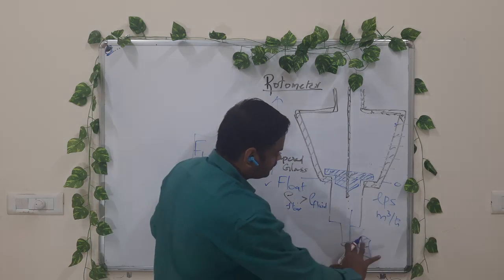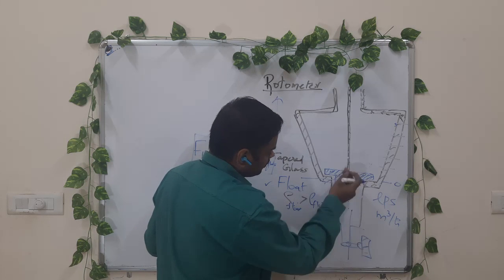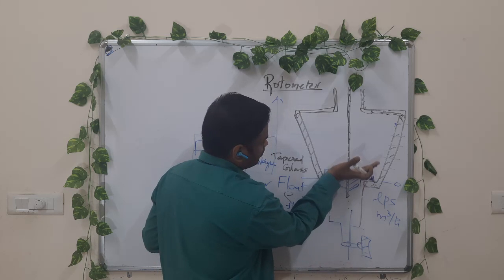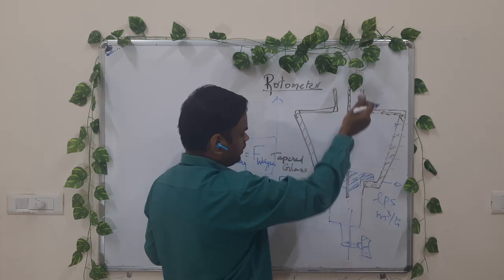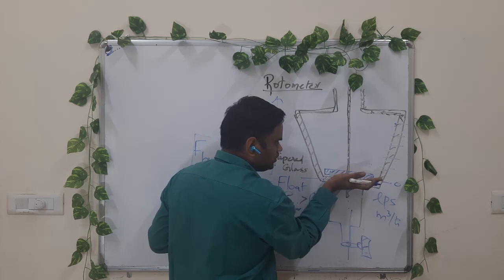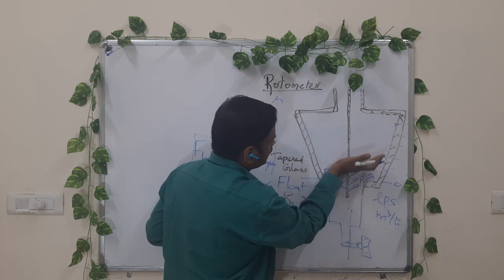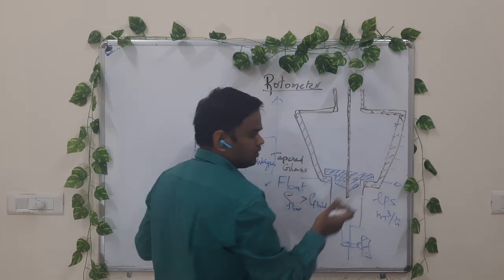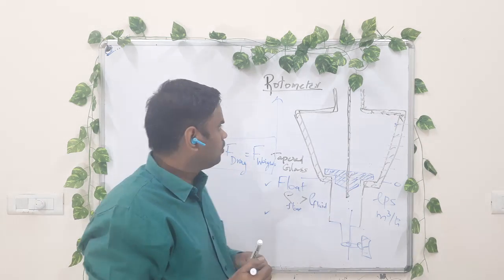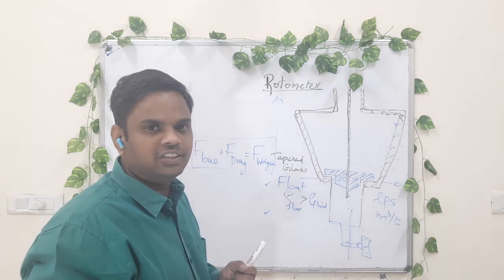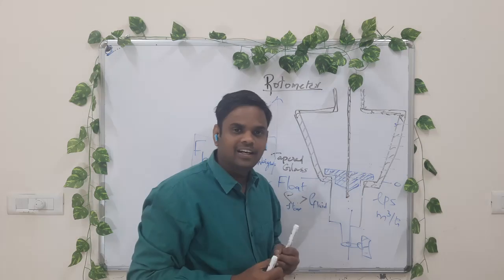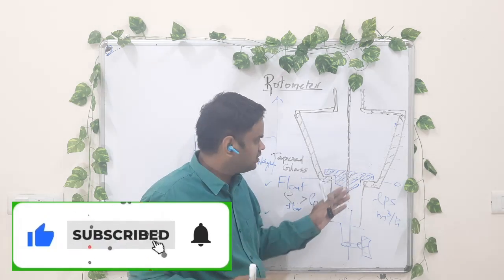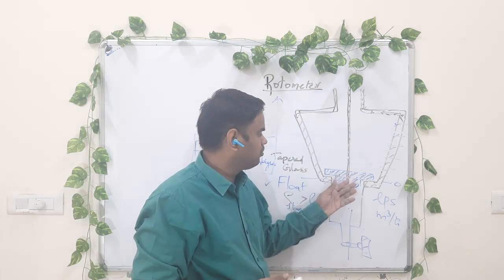By adjusting the valve here, we are going to change the volumetric flow rate. When we change the volumetric flow rate, the float will move from bottom to top with increase in volumetric flow rate. When it is 0, it will be at the bottom position, and when it is fully open, it is going to be at the uppermost position. And it's readily made. So the advantages of this type of rotameter device is it is simple in construction, and it gives a direct reading, no calculations involved. So even a supervisor with less technical knowledge is able to measure the volumetric flow rate.